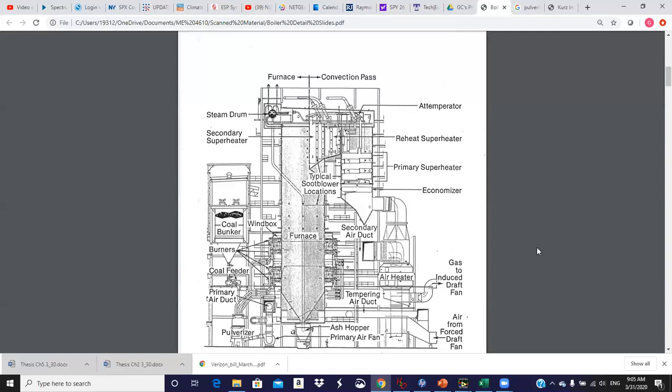And so the steam is then reheated, and then it exits there and goes back to the intermediate pressure or the medium pressure turbine, expands through there, and then goes straight through the low pressure turbine sections, then to the economizer. Of course, we have extractions from the various steam turbines as the cycle is designed.